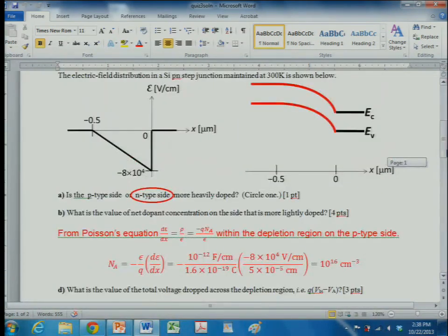And then finally, to complete the energy band diagram, what I was looking for is that you knew that the energy bands, EC and EV, are higher on the P side, so that's 1 point, and that the curvature is bending downwards like this, not concave the other way, and that you draw a uniform band gap. So those are 3 aspects we look for on that band diagram.